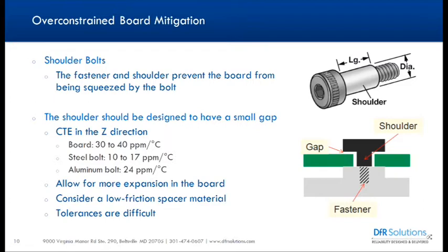And I've seen it where I took the bolts out, and you can see inside the copper, the plated through hole for the mount point, you can actually see the striations of where the bolt was biting into the copper. You don't want to do that.